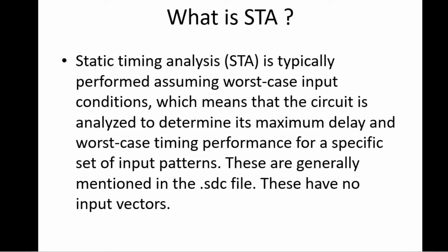And no input vectors are applied. Why are we not giving the input vectors? Anyone can say, just for interaction. Because if we give input vectors, then we are checking the functionality also, but we don't need the functionality. We just want to meet the setup and hold time here.